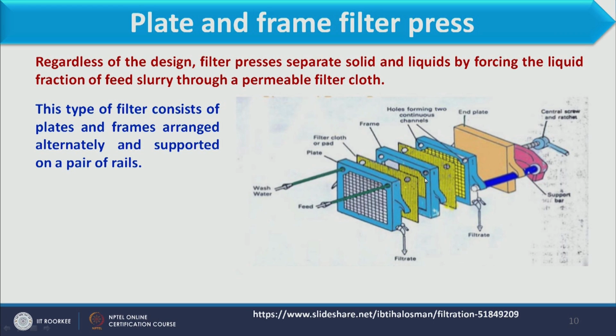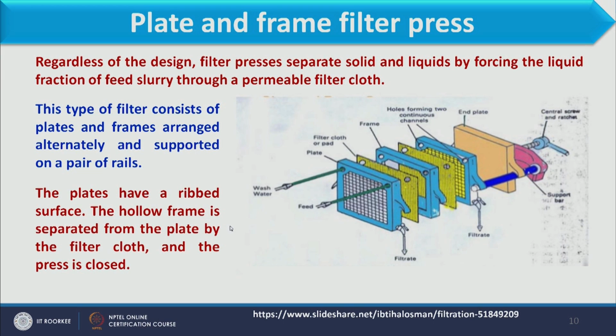However, the frame has a hole, and though it is empty in between, whatever liquid is coming is spread in this region. Once it is spread, it falls in this way and that way. As both sides of the frame have filter media, once feed enters, filtration takes place at both sides of the frame. So this is the basic working of the plate and frame filter press.